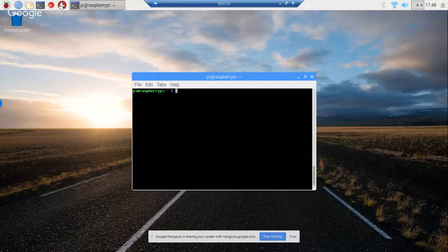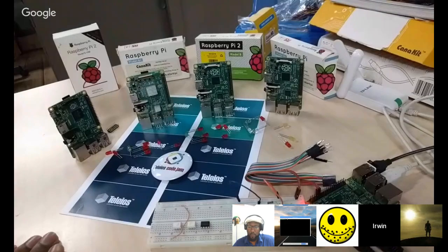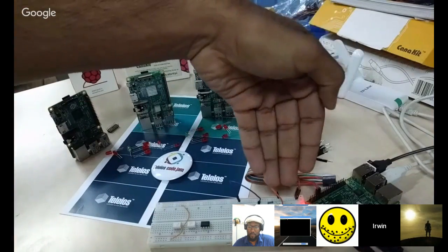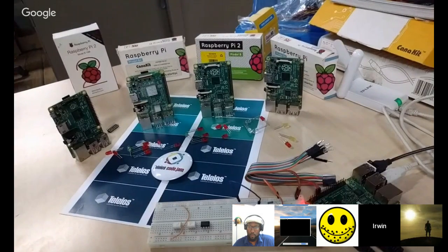Yeah, so the circuit. I don't know if you all saw the camera, the stream for that. So the circuit is, we chose to keep it simple. So nothing else besides the basic Pi, and I'll explain the circuit connections soon. But it's just a basic LED to the GPIO to a resistor to ground.